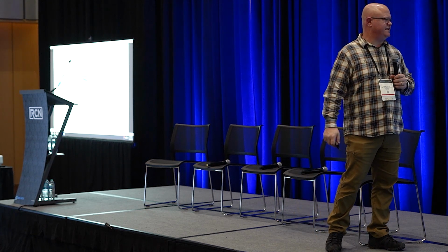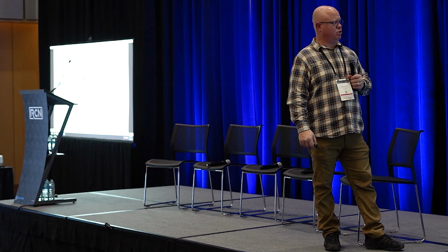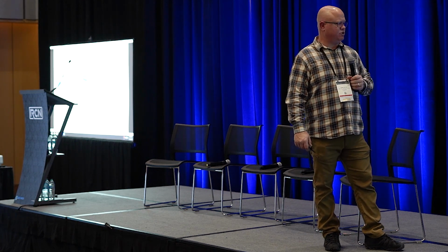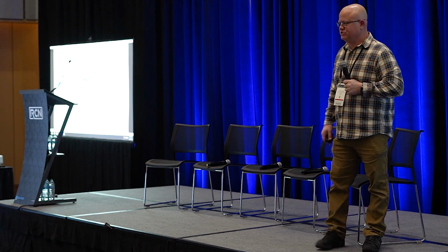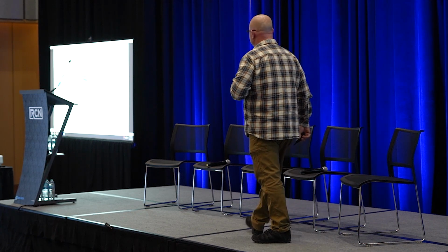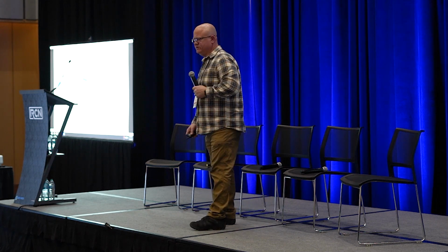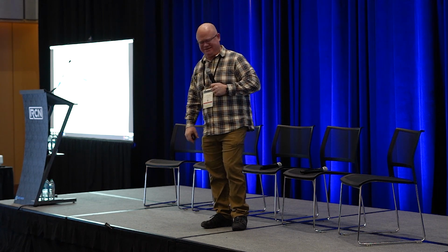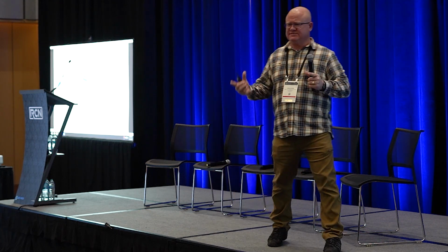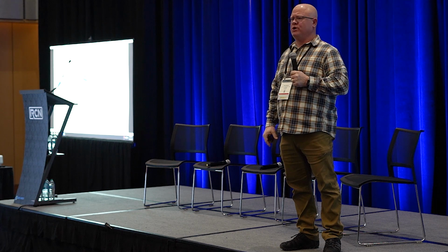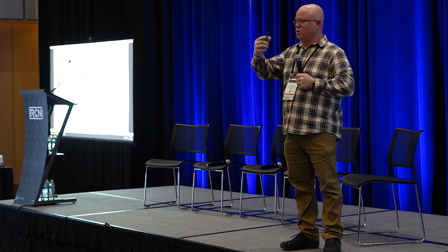So we do all the data aggregation and preparation inside of Recap Pro, and then we jump into Revit and we start using the mesh information in Revit. I don't want you to think that you can only bring mesh files into Revit. You can bring the point clouds into Revit. We actually had somebody come by the booth today and ask us about that, if there was anybody that just took point clouds and actually built the Revit model from the point clouds. So that is something that can be done. Those files can be brought into Revit, and you can just start drawing walls right over the top of the stuff.